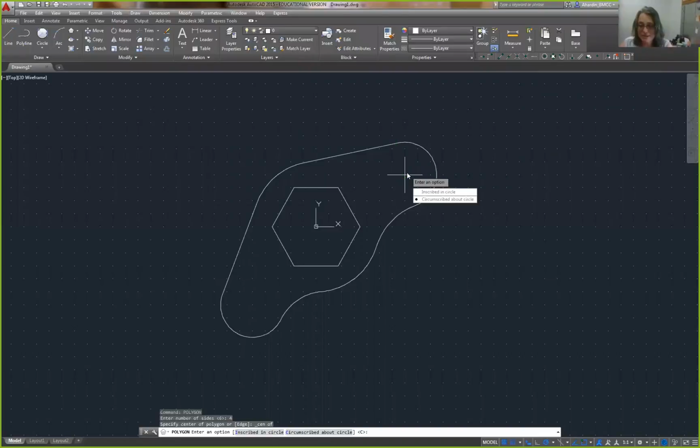We can click, and we again have got a side-to-side dimension, so we're going to circumscribe this about a circle. And our radius is 10 because our total dimension side-to-side is 20. So this will be 10. And there is our upper square keyhole.